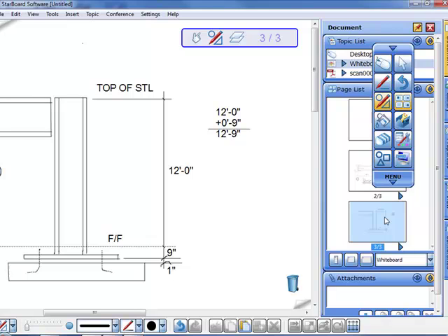All right. I guess it's kind of like nominal. You just have to remember for your bill of materials, that's what you would put there: the 10-foot 5 inches, so that when they cut these pieces in their shops, they cut it to the right length, because otherwise you're going to have an inch difference. That makes sense. And if you're trying to fit this in a specific place, you can't have an inch off. You could throw everything off, because if you're doing a pipe rack and you're off by an inch, then the pipes are not going to come out right.